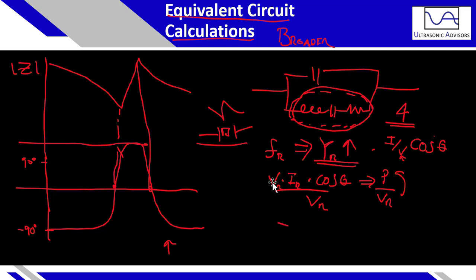So in general, we look at admittance as a generalized way of looking at voltage input, current output. But if we look at the real admittance, it's going to be correlated to power dissipation. This doesn't occur for impedance. The same relationship can't be used. You can't look for the minimum real impedance.